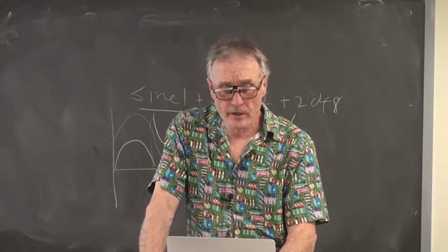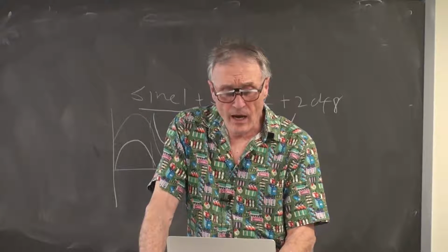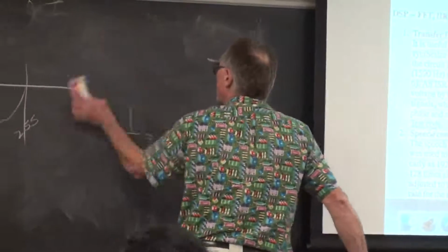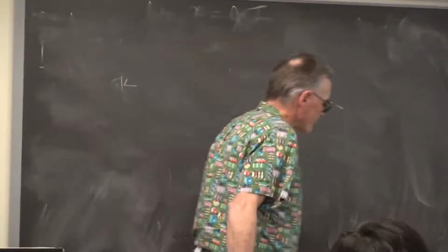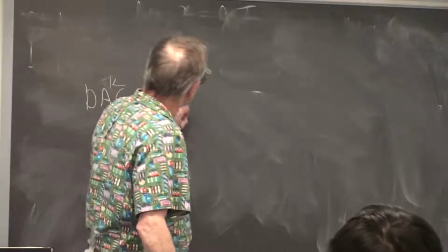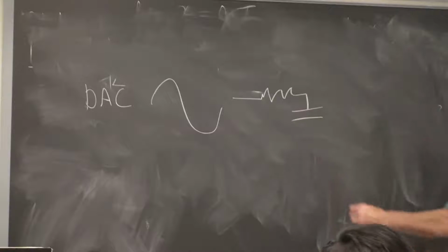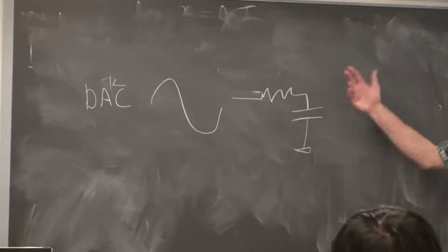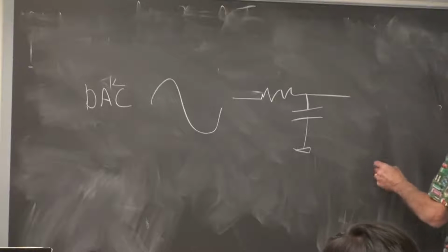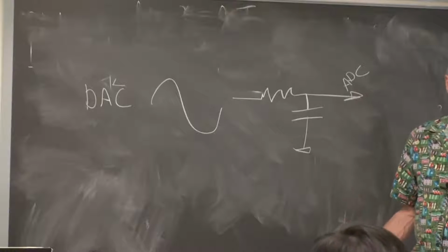So let's look at a little bit of code here. All right, so this code is what I've been geeking it up with for the last 2 or 3 weeks. What I wanted to do was to use a DAC to produce a nice clean sine wave, feed this into some complex impedance, and for testing I'm just using an RC circuit with a cutoff of 10,000 radians, and then feed this back into the ADC, measure the voltage, compute the phase and the magnitude.